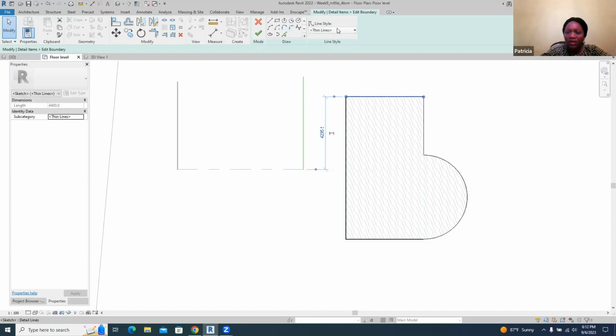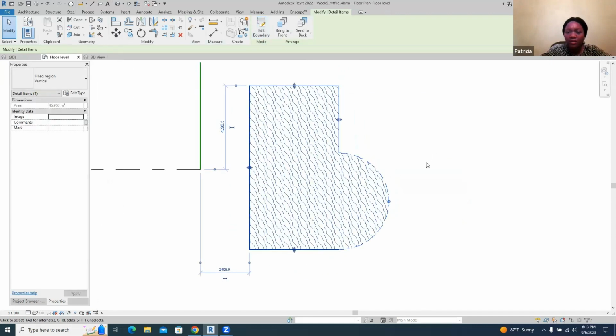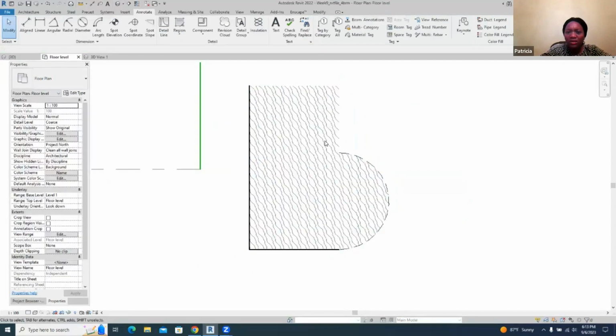And then we can come over here and make it look like it's continuous by choosing invisible here. We're making invisible here. And then I can make this hidden line. So when we check that, you see the kind of effect that creates for us. These ones are hidden, this is hidden, and these ones are invisible, and then here's hidden, and these are wide lines. So you can see the kind of result or the output we want to get graphically.